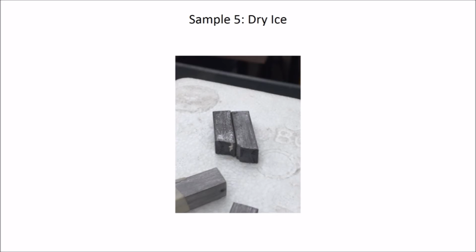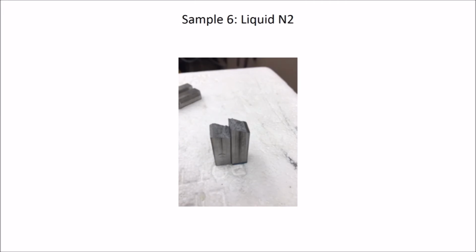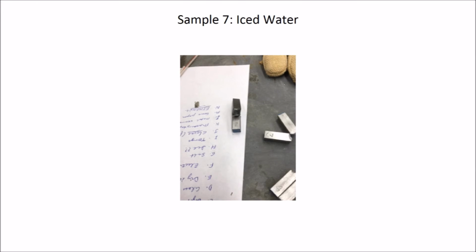Sample 5 had the same result on dry ice, with a very smooth fracture surface. Sample 6 had a very abrupt brittle fracture, and sample 7 from the iced water had a relatively brittle fracture, almost completely flat.